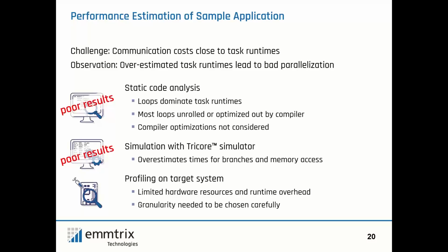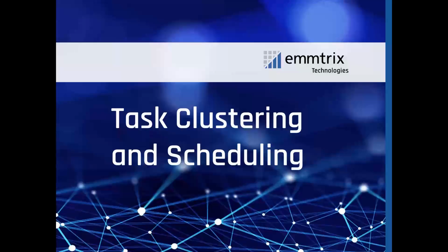So what we did is we actually did profiling on the target system, and our tool also has the possibility to auto-generate profiling code. What needs to be considered there is that you have limited hardware resources, which will be used by your profiling data, because the profiling data has to be stored on the system during runtime of the application. During runtime, you will have extra functions you need to call for the time taking and so on. So this needs to be applied carefully, because if you add too much profiling code, your application runtime will not correspond to the one you would get without profiling. In our case, this worked pretty well. So this is what we chose for that sample application.